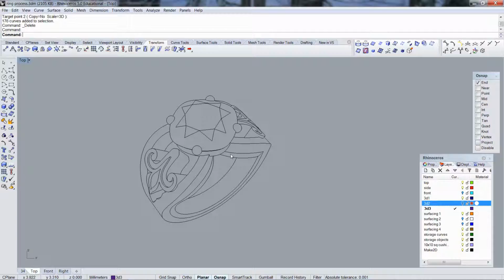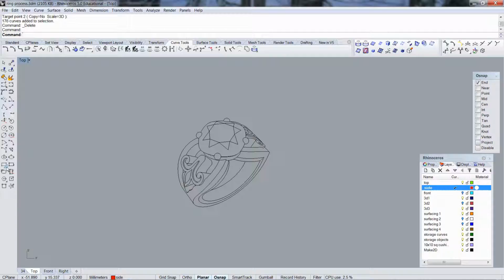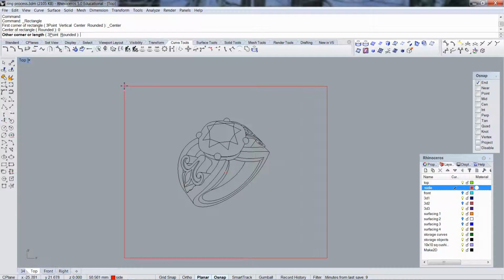Okay, so I have this, and I will now export this, but before I do, I'm going to surround it with the red square like I always do with my exports from Rhino, so that when I take it into a 2D graphics program I don't end up getting artifacts around the edge of my image. So make the square center around 0, pull it out, that's fine.